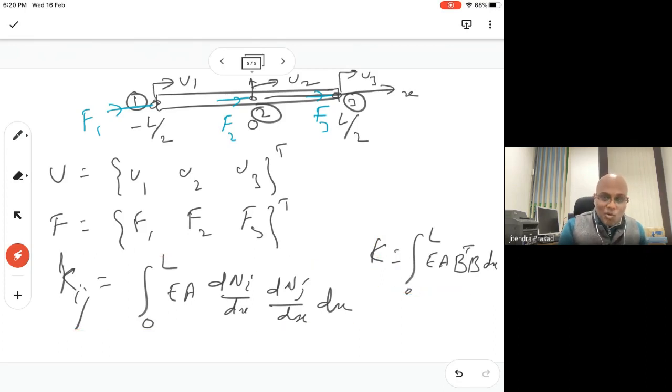Once you know how the weak formulation looks, for a 1D problem this is the standard that we can use. For what kind of problem? For the 1D elasticity problem, it is valid. Otherwise you have to look at the weak formulation. But we have already looked at the weak formulation, and found for this problem, when we were working on 1D with the single two-noded element, that before that we converted it into a weak formulation. From there we got this. So the same thing will be applied here also.